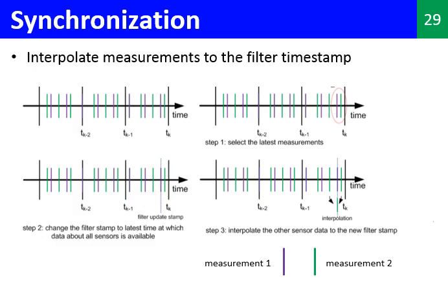The next thing we are going to do is interpolate the other sensor reading, which is in green color, to this new timestamp. Now we have synchronized sensor readings, because the purple one is at that timestamp, and we did an interpolation for the green one to that timestamp, and also we predicted only up to this timestamp. So everything is available for this timestamp, right?